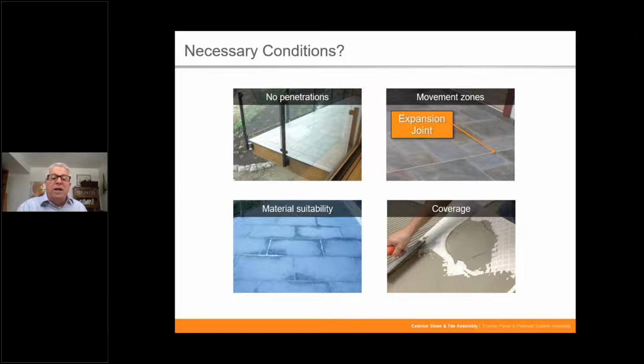It's always a good idea to keep that away, not only from the waterproofing, but when the tile wants to expand and contract due to thermal changes, you're going to need to leave a lot of room around any kind of railing or post that you're putting through there to allow the tile to move independently and not be pinned in by any kind of a column or a post or a standard or anything.